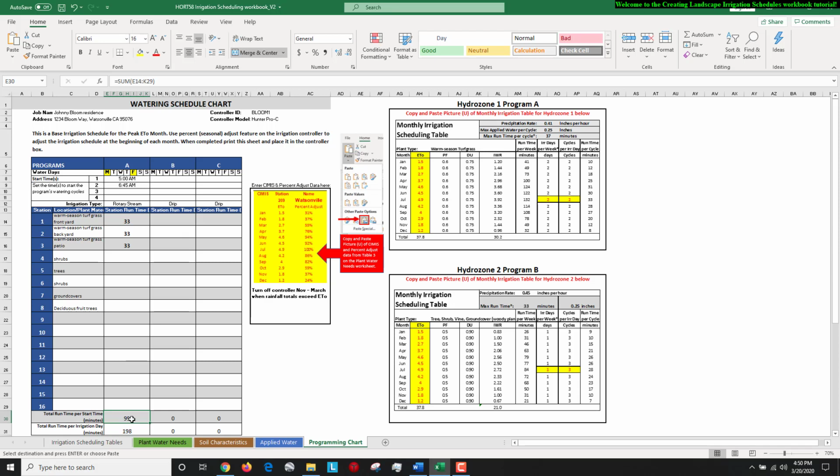So in this case, that would be approximately 6:39 a.m. So I chose to have runtime 2 start at 6:45 a.m. That allows plenty of time for a soak period between the cycles, and it avoids overlap between the start times and the end times of the 2 cycles.